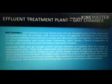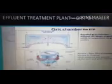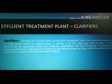Next are clarifiers. Clarifiers are settling tanks built with a mechanical means of continuous removal of solids being deposited by sedimentation. A clarifier is generally used to remove solid particulates or suspended solids from liquid for clarification and thickening. Concentrated pollutants that are discharged from the bottom of the tank are known as sludge, while the particles that float to the surface of the liquid are called scum.